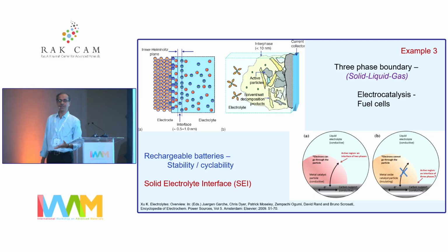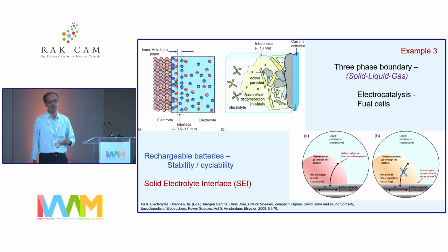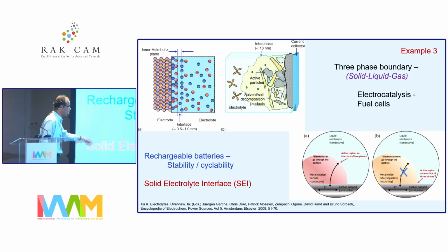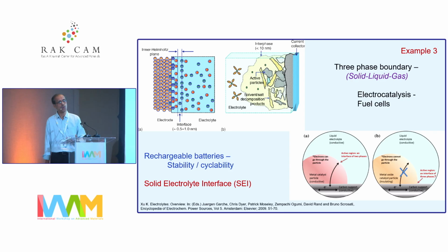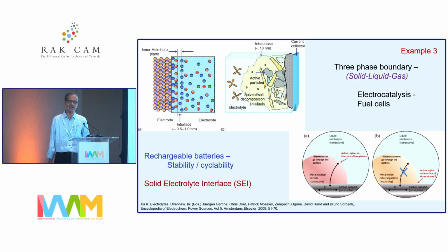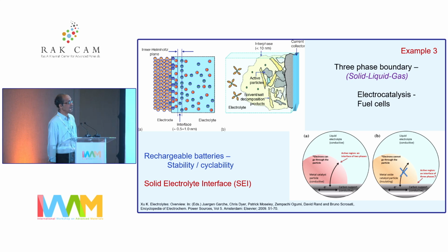The lithium battery that we're all using lasts for about 500, 600, 700 cycles simply because of this particular aspect called the solid electrolyte interface. When we charge and discharge the battery, we essentially have a film that gets formed on the surface, which is ionically conducting and electronically insulating. And this was proposed by Doron Aurbach and Pellet at Bar-Ilan University several years ago. And this is what is responsible for the lithium batteries to work for a large number of cycles.